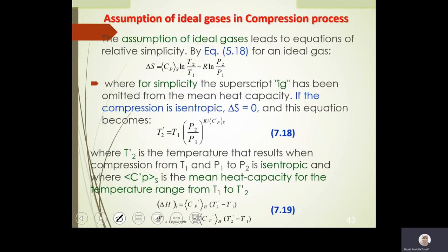Okay. The last thing I want to talk about in this chapter is what if the same question was given, the one that I just explained, was given for ideal gas. It is not actual data. It's not from the thermodynamic table, but it is ideal gas. If it is ideal gas, it is the same thing. Same thing means if you have been given the efficiency, for example, with the turbine, it's delta H over delta HS.